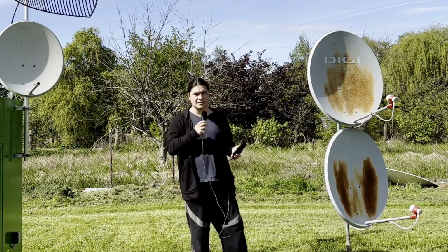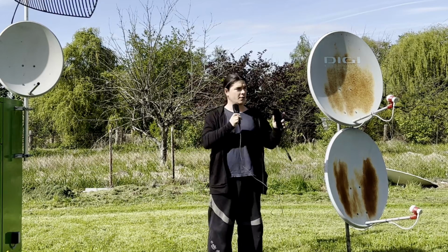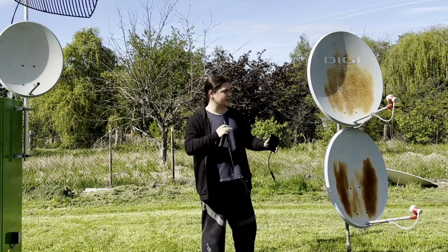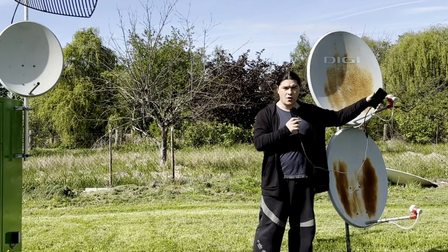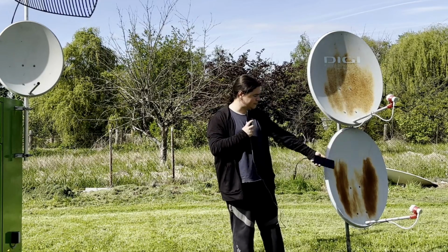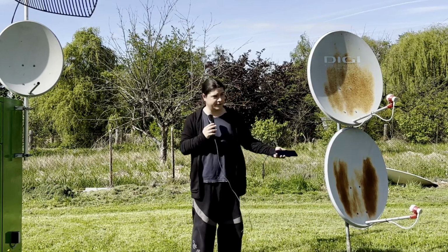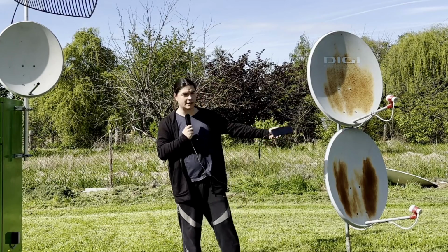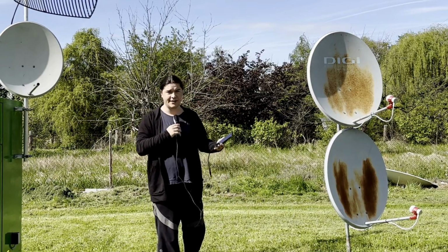Together with that, there's also the fact that it uses the 3 centimeter amateur radio band for its downlink, which, if you don't know, is around 10.5 gigahertz, which, if you still don't know, is right at the lower edge of the range of frequencies that commercial off-the-shelf Ku band TV LNBs actually work at. Both of these cost, I don't know, like $5, and they are working perfectly fine for the reception. Combined with the fact that a small aperture dish antenna works, something like this, or even this dish antenna works perfectly fine and has enough gain for it.